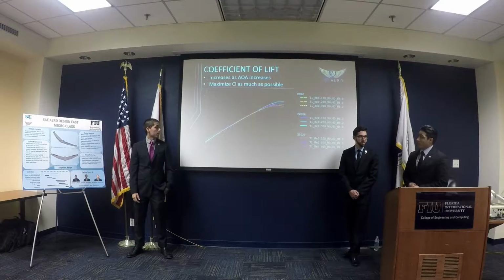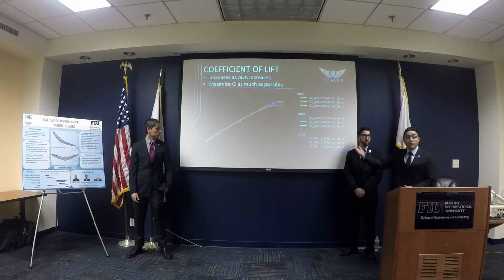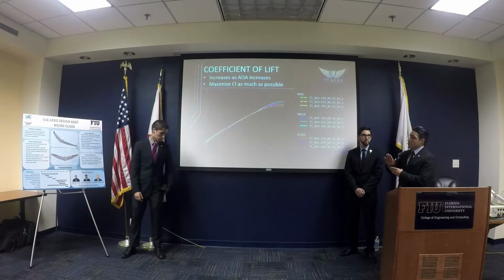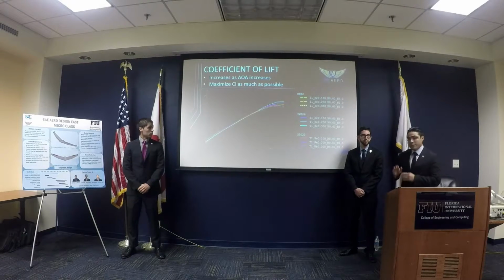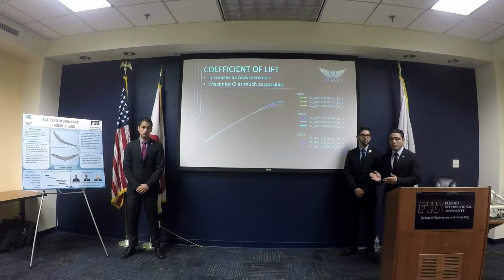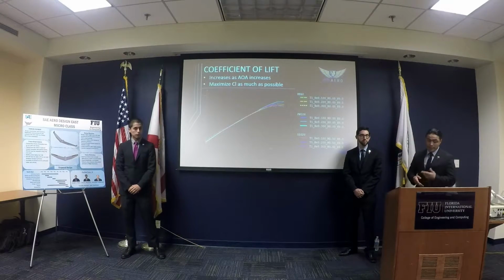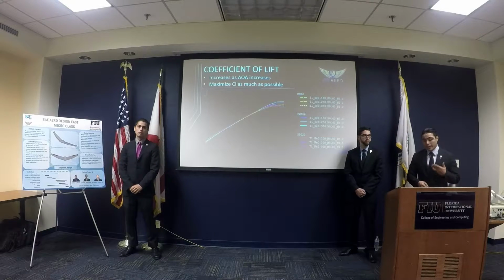As my friend Wladimir was explaining, the coefficient of lift is also very important. As you increase the angle of attack of the airplane, the coefficient of lift increases as well. There's a boundary where this coefficient of lift is going to break in a way that as the angle of attack increases, you're going to lose some lift. And that creates instability for the aircraft, and you can definitely crash the aircraft.